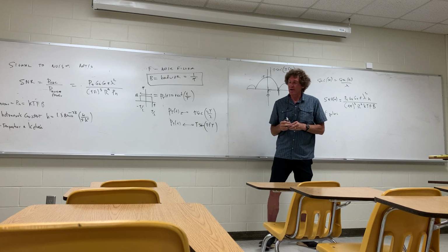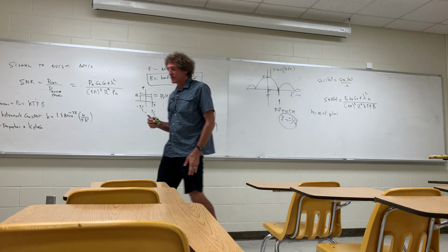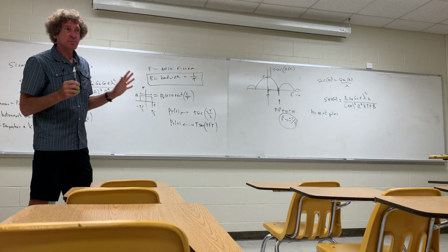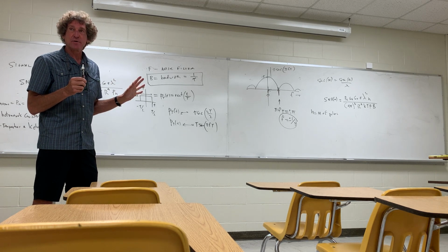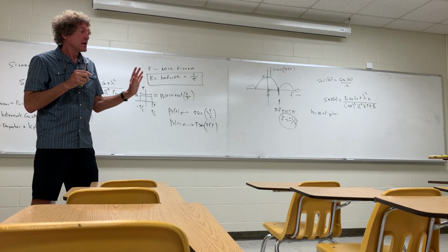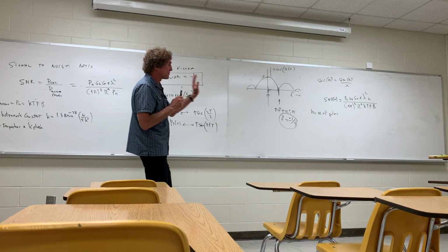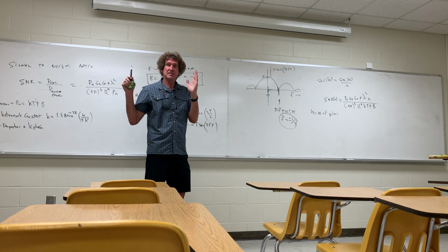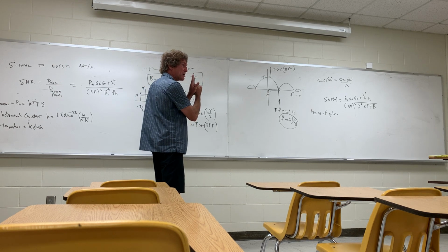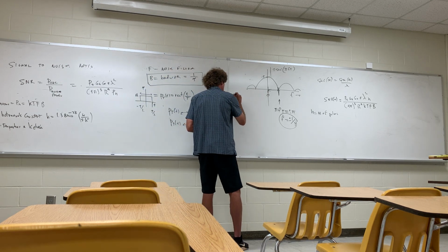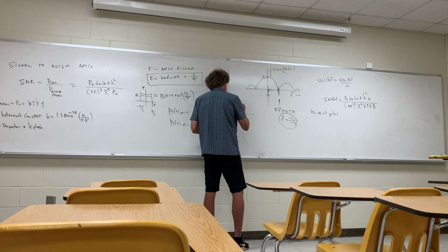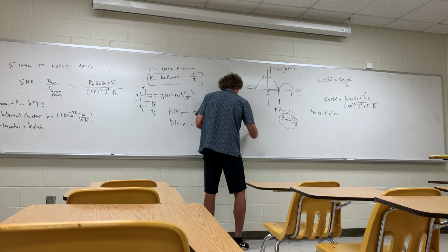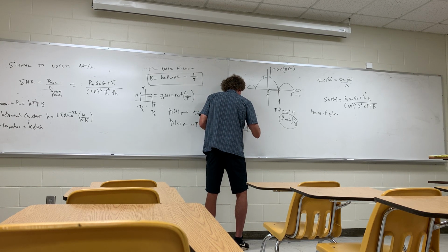And here's why I try to make sure you understand this. You all know that noise power is not additive, white noise. It's because it's uncorrelated. So I send a signal, and the signal comes back, and I record that as it comes back in time. So I have a temporal recording of it. It may look like this. My transmit signal will be this. This is going to be baseband. What I receive back has a time delay. Then it comes back greatly reduced and it has noise on it, right?